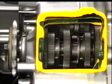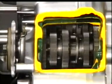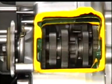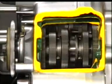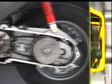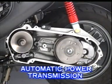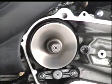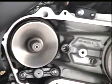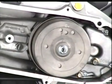As the rider shifts through various gears from low to top gear, the gear shifting cam and gear shifting fork work together to change from one speed to the next. There is also a type of automatic transmission which uses a V-belt. This gear-changing mechanism consists of a drive pulley, a driven pulley, a drive belt, and a centrifugal clutch built into the driven pulley.